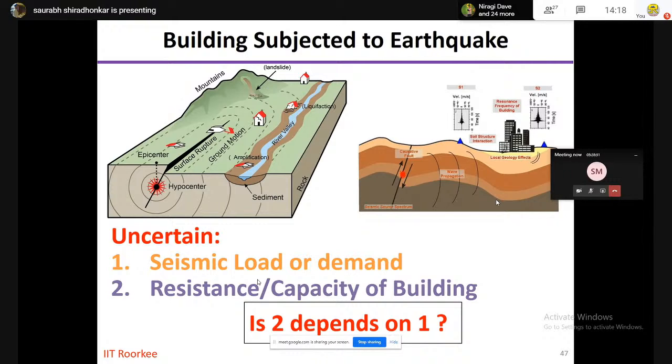You need to do the simulation that we have seen in the previous slide, taking one value and doing the analysis again and again. This sounds very simple when it comes to simple formulation. However, when it comes to earthquake ground motion, you need to understand that estimating inelastic response is a very tricky business.